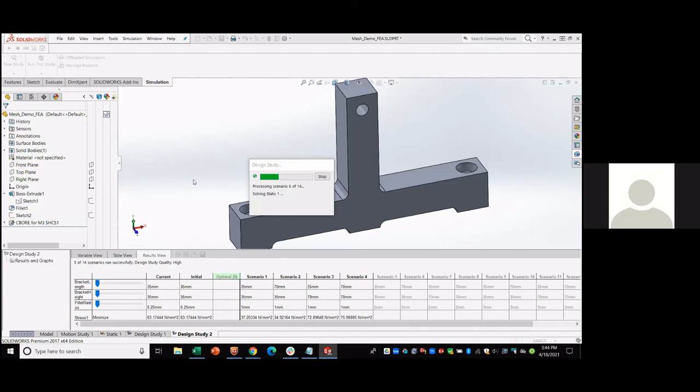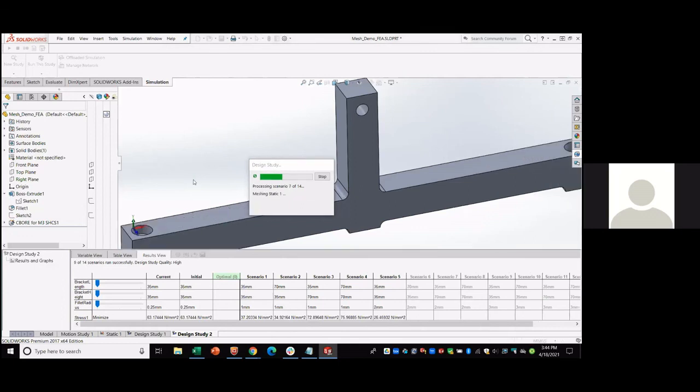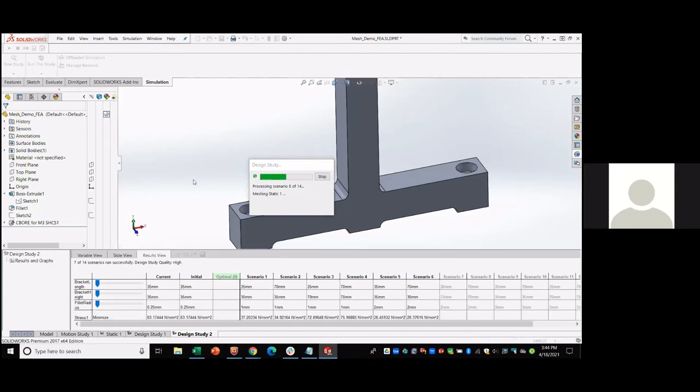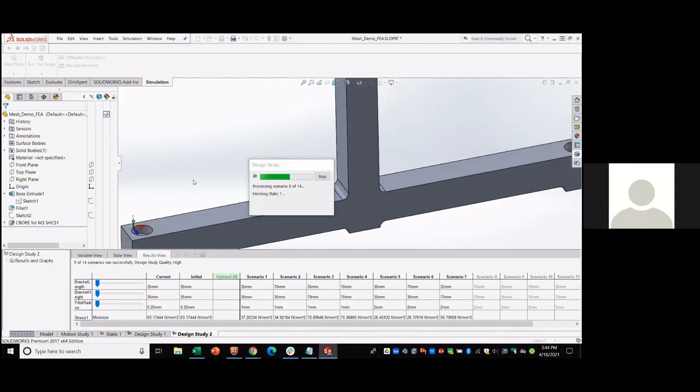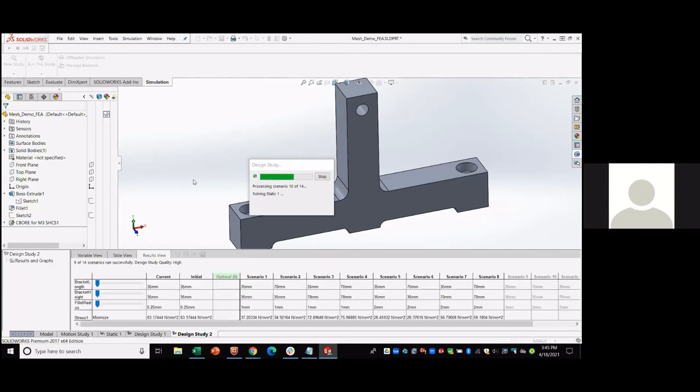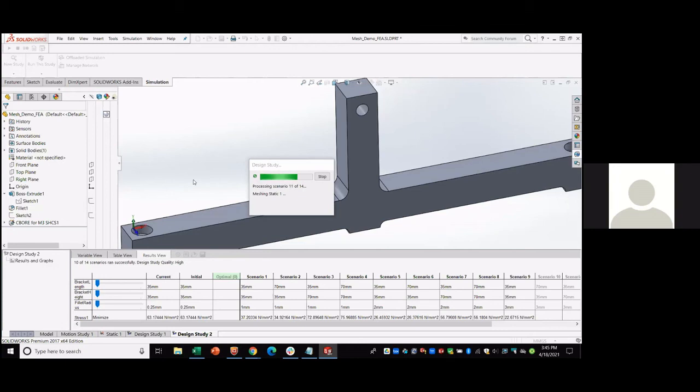And because we went through the work to determine what the optimal mesh size rules are, we know that the results between these different models are going to be useful and comparable. You could, if you didn't know the rules for mesh density, create a design study where you have different dimensions on your parts, but the number of elements across the fillet could be different as you shrink and grow the fillet. And you could be getting inaccurate results for small fillets that may make them look better or worse than larger fillets.